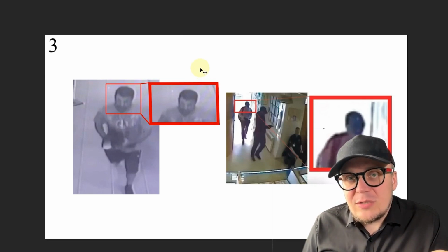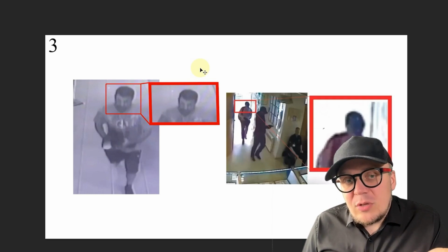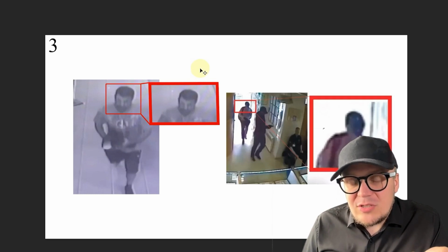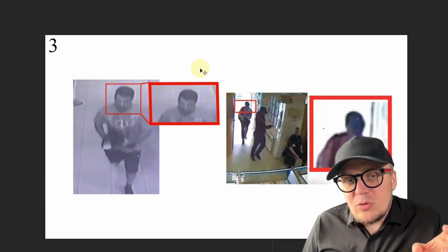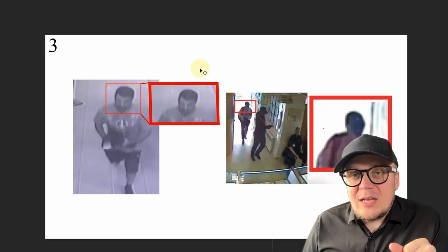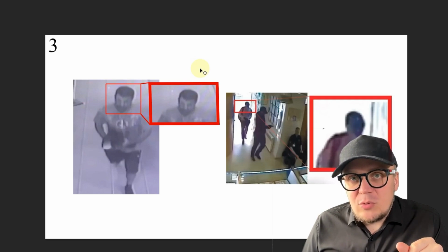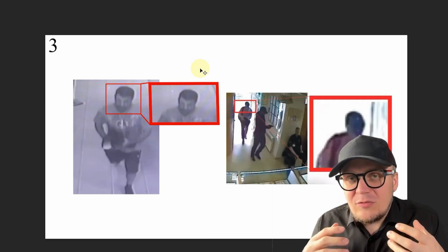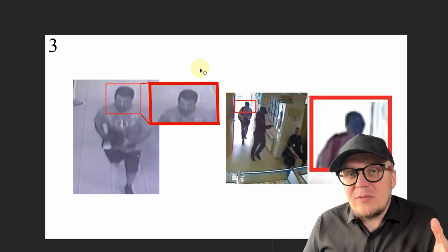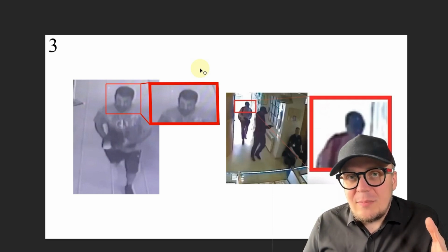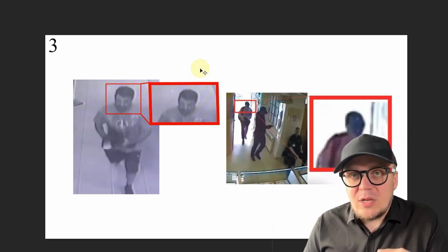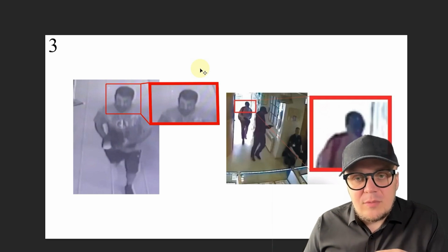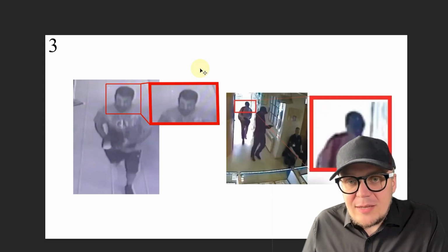Then there's the situation where you spend a long time choosing, researching, understanding what a sensor is, what a processor is. You choose based on the lens, but you didn't analyze your specific area. For example, you needed your camera to capture faces and car license plates from a distance of 20 meters. But you chose a surveillance camera that can see faces at a maximum of 2-3 meters. Beyond that, everything is blurry. Or like here, everything is pixelated.